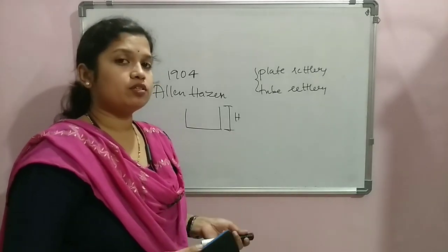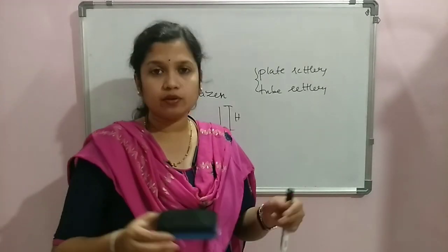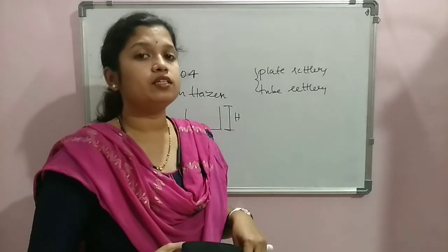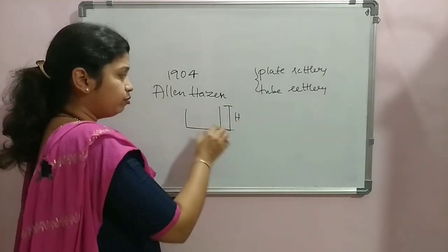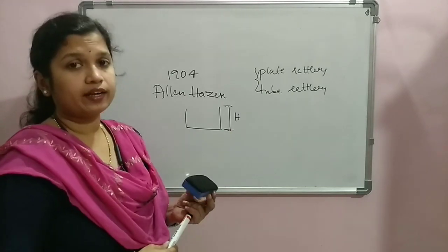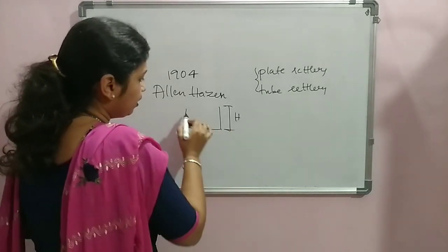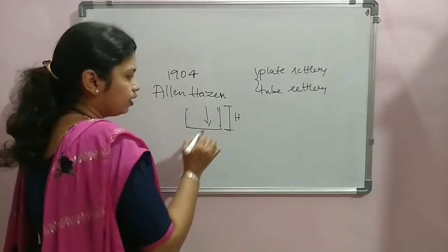To achieve this is very difficult. Why? Because in typical sedimentation, we know we have to increase the area in order to make the velocity slow. So to overcome this, when we decrease the depth, we have to increase the area of contact. See, in a typical tank, this is the only area coming under contact, so particles come down and settle under gravity.